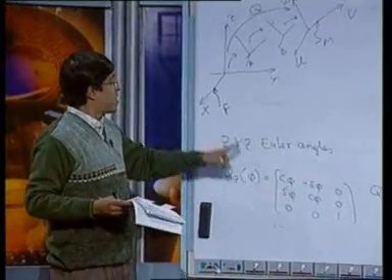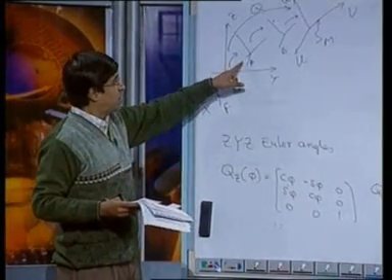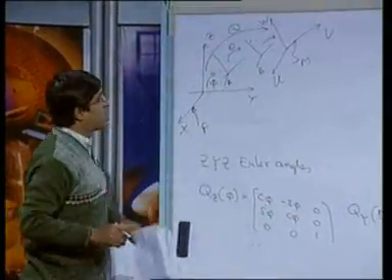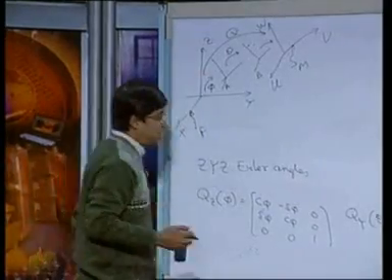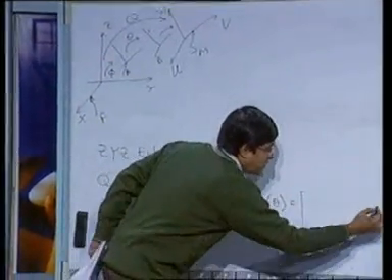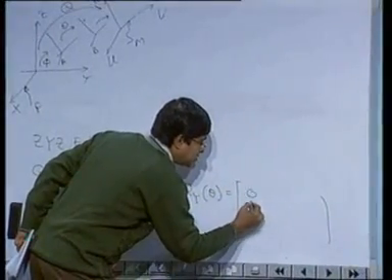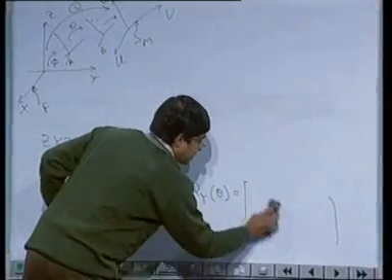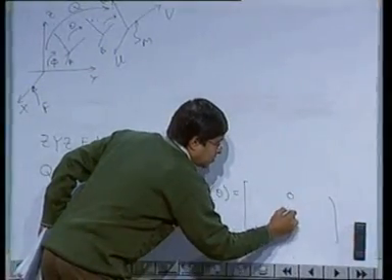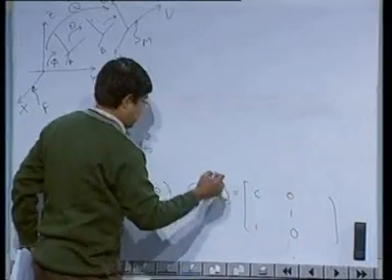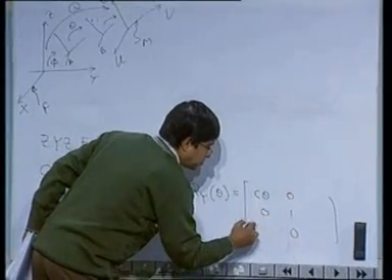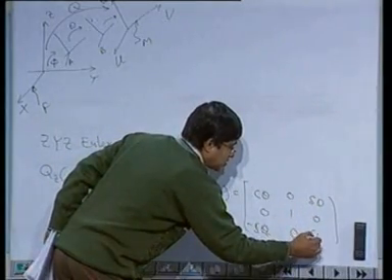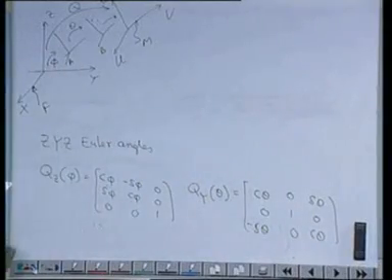After I give the rotation phi, it has moved from frame F to frame A, and then I am giving rotation theta about y of frame A, so that it reaches B. That can be verified as: this is 0 1 0, so this will be cos theta, 0, minus sin theta; 0 1 0; sin theta, 0, cos theta. This you can check yourself.